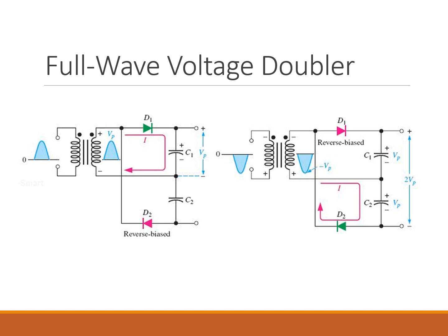What results with this type of circuit is you do get smoother charging, you get less ripple, you're utilizing both cycles. So those kind of make sense. And it's better than the half wave because it charges both capacitors every full cycle, not every other. The output is just more continuous and stable, and it's better suited for slightly higher current needs, but it's still kind of better for things like high voltage bias circuits for CRT tubes, laser printers, ionizers, and stuff like that.